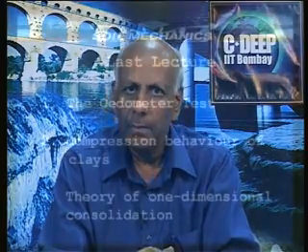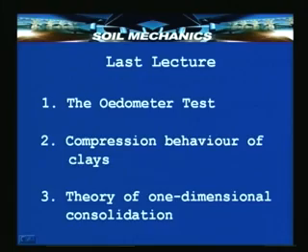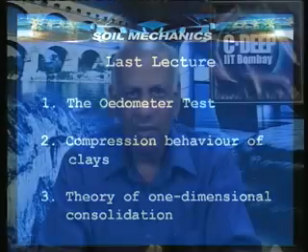Then we started discussing the theory of one dimensional consolidation. First of all, we said that one dimensional consolidation is an assumption, and that it is valid under certain specific circumstances. The major circumstances are a very large loaded area and a deep seated clay layer.